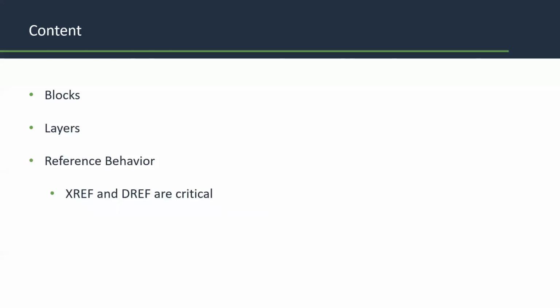Because just like view frames, we're going to create new drawings, and we don't want to create copies of our master objects. We only want to look at them and keep bringing them through into our new drawings as those are being referenced. So again, we want to avoid those live Civil 3D objects. So with that overview, let's go ahead and get into the software.